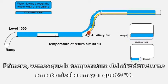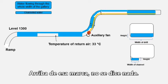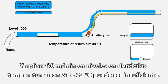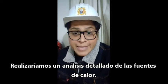To begin with, we see that the average temperature of the return air at that level is higher than 29 degrees Celsius, so we could not apply what the Peruvian regulation dictates, since it only regulates up to 29 degrees Celsius. Above this mark, it says nothing. And applying an air velocity of 30 meters per minute to places where temperatures are 30 or 31 degrees Celsius may not be enough. What should we do then? The answer would be a detailed heat analysis.